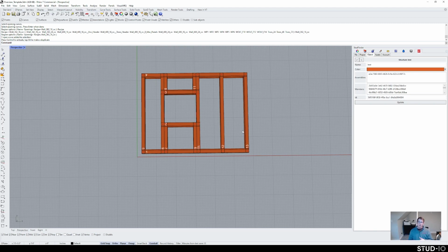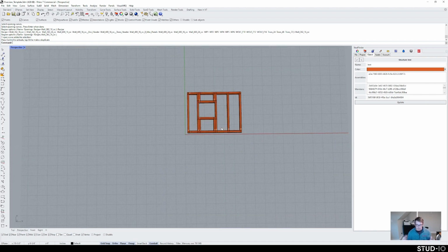So what you really want to do is use recipes to get really, really close. And then any last minute panel overrides, like let's say you needed to double up a stud or move a stud, you want to do that at the end, right before you go to fabricate. So that is kind of regions. So this SF create region can be done one panel at a time.